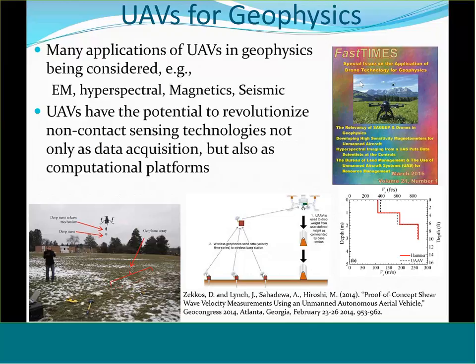Just recently, something that I think we're going to see more in the near future, we've been playing with using drones for seismic geophysics. So these are some of the experiments in the lower part of the slide, where we're using a small drone to drop a small weight, and we generate a seismic wave that propagates and is picked up by the sensors. And very, very soon we'll be doing this at a larger scale. And what we can see is actually that we should be able to use drones for seismic geophysics, and potentially this technique could be a portable high energy input technique, much higher energy than a sledgehammer.